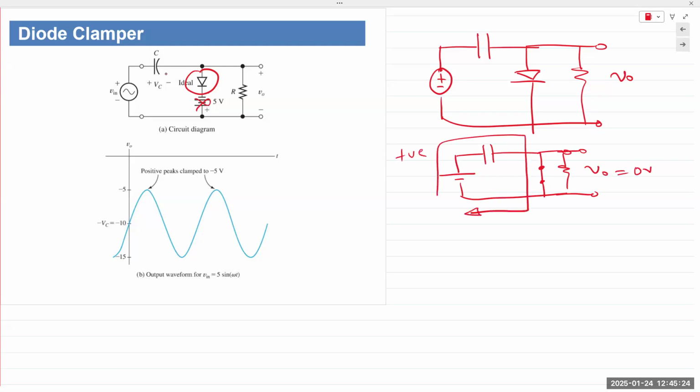What happens to the capacitor? EE201, chapter 3. It charges. Plus minus. Current is flowing from left to right. Passive component, passive sign configuration. If it's flowing from left to right, point of entry is always plus, point of exit is minus. Capacitor charges with plus on the left, minus on the right. Now, negative half cycle, what happens?